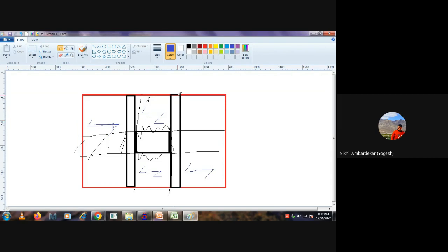And I added a beam here because this is the shorter span. Someone may add a beam here also, but you would be increasing the beam depth, because it is not a critical span. By observation, if this is my shorter span, I will provide beams here. So here the plate elements will be separated in between these two beams. If suppose the thickness of the plate is 500, then for this portion you can increase the plate thickness. You will get some additional advantage of additional depth, maybe 800.